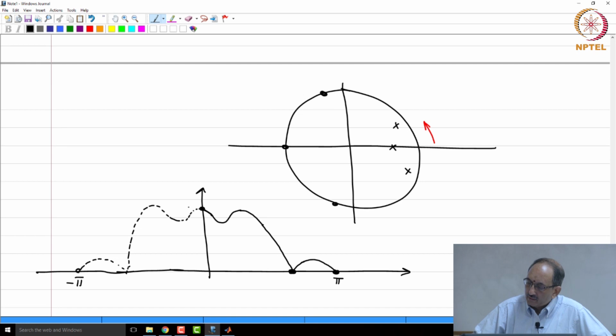Since this is drawn by hand, it is not precisely the same, but the intent is all these peaks are exactly the same point. Even the dips have exactly the same dip value. So, this is what is called an equirippled response, and there are filters that have this kind of frequency response that is equirippled, that is these ripples have the same height. Unless I mention that to you, you cannot draw this kind of plot. This is what is called an elliptic filter, all right.